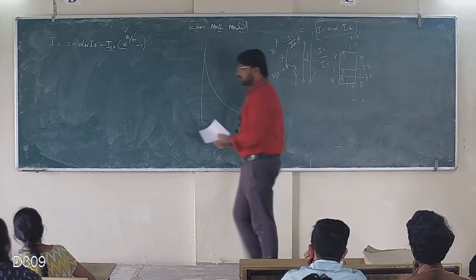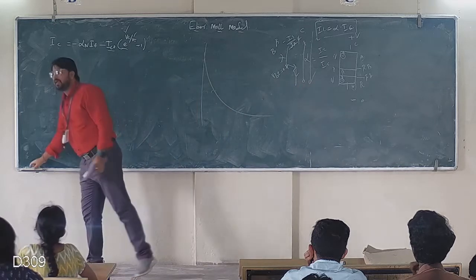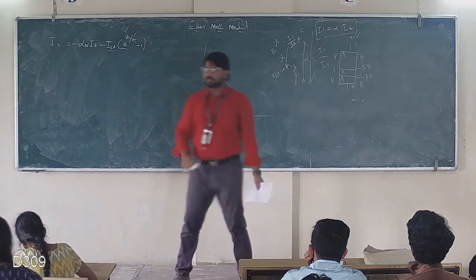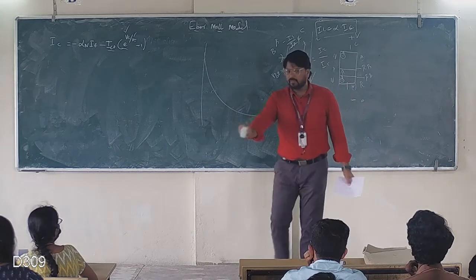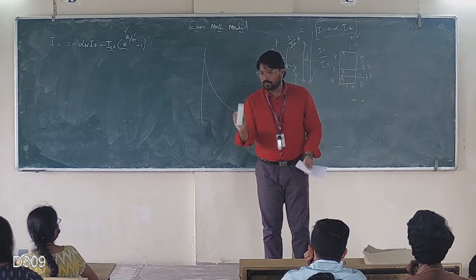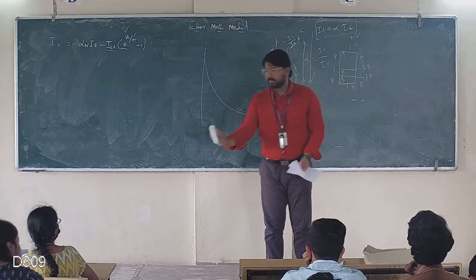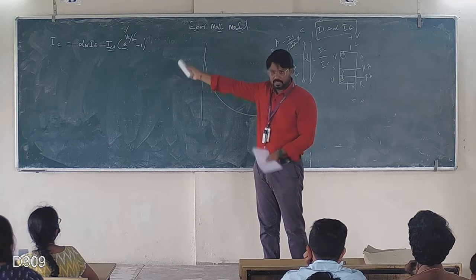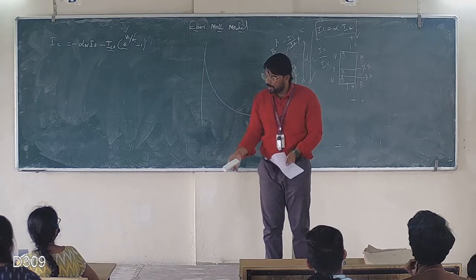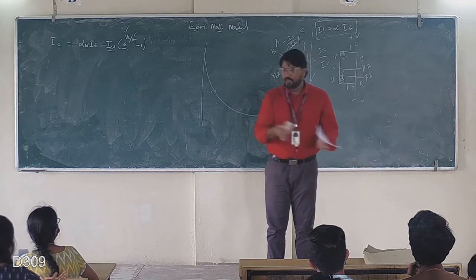So this is the generalized expression for any transistor. If I consider collector current is equal to IE. But what we have done in inverted mode is that collector and emitter are interchanged. In general, IC equals this, but we interchange collector and emitter.